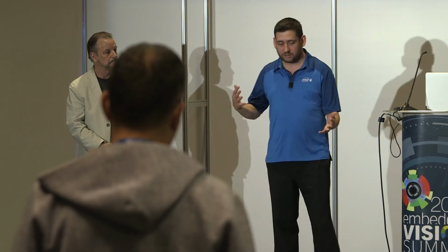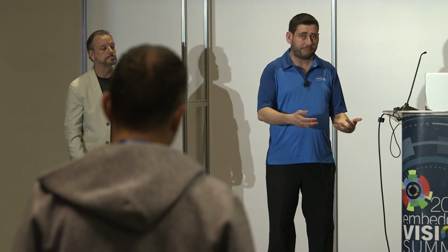I have two small questions. Do you have relocalization on your model? Yes. It's actually relocalization, not like loop closure. Can I save a map and then relocalize? Yes. The module itself is building a map. It has several dozen megs dedicated to that, and you can actually download the map and use it later or with another T265, and the device will relocalize to the map.